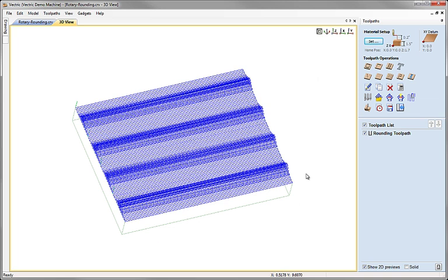And before we conclude, let's just take a moment to summarize what we've looked at through this video. Really, the main thing we've been trying to get across is the specialty tools that are available for setting up rotary or wrapped jobs. First of all, it's important when you're doing any kind of rotary job with VCarve Pro or Aspire that you're going to use the gadgets in order to do the wrap job setup so that it knows the orientation of your rotary axis, it gets the size and the diameter and translates those into the correct X and Y values so that when it's wrapped, everything is going to give you the sizes you expected.